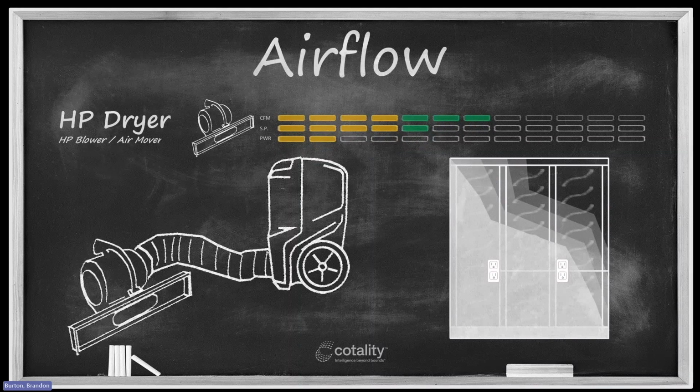So the attachment here that I'll talk to is a turbo vent. There's a couple of different styles of these turbo vents that are out there. In this particular case, probably what I would lean on is the turbo vent that attaches to the snout of your air mover, then reduces that to 3 4-inch ducts that go out to additional 2 3-foot wide turbo vents. So I'd have one blower powering multiples of these vents.